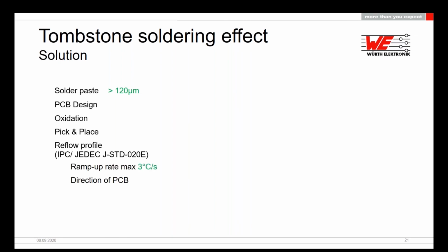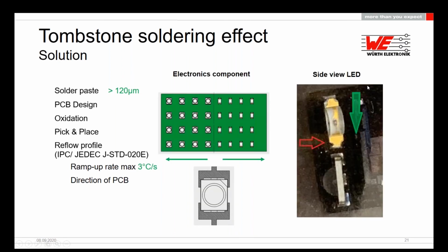And it's recommended to let the side view LED run in horizontal direction in the reflow, as shown like the green arrow, not in vertical. It's different from the normal electric component. And the last thing we can recommend, please keep the speed of the reflow fan as low as possible.